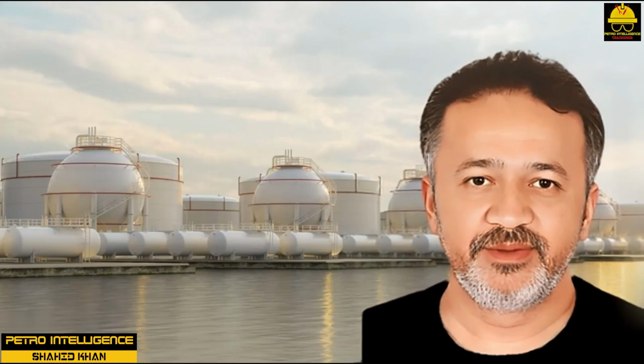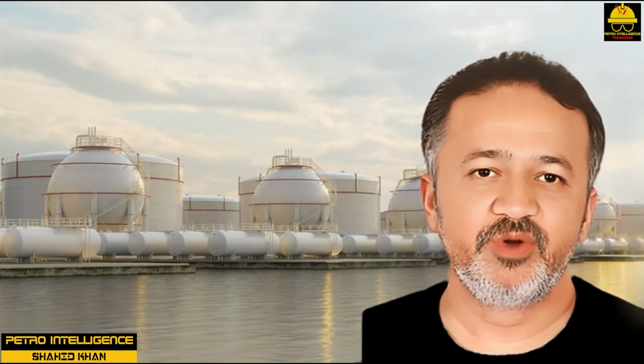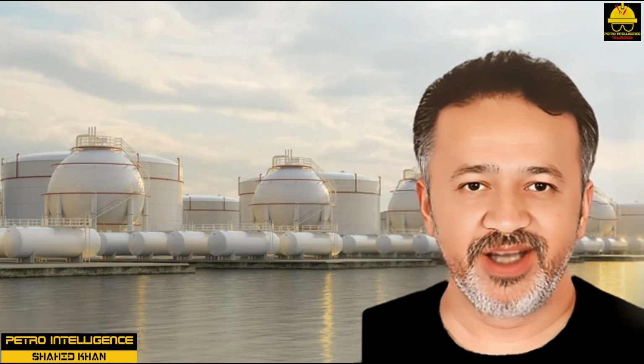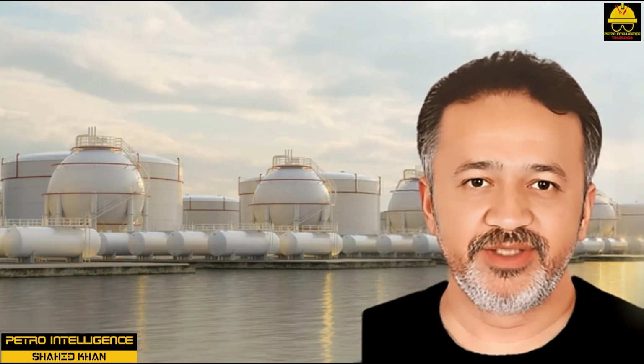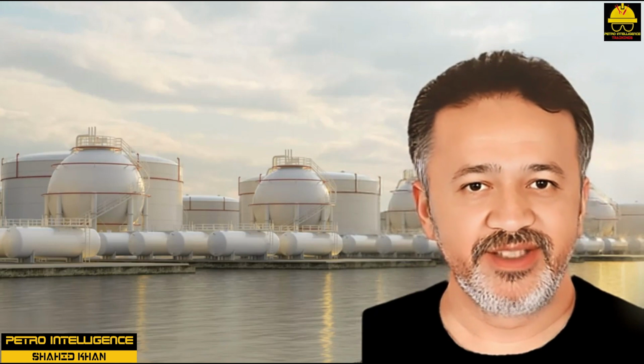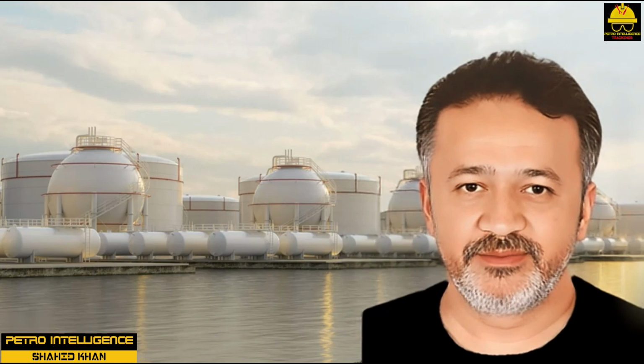Pressure. The equipment is designed for normal operating pressures plus an incremental increase in pressure to allow for operating upsets. The relief valve on the equipment or in the system is set to relieve when the design pressure is exceeded and is provided for equipment protection and safety of personnel.